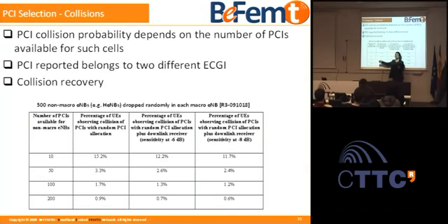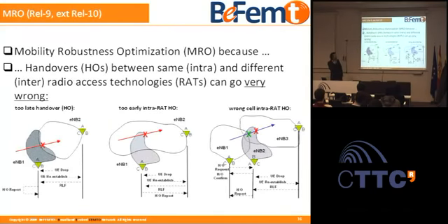The remaining 200 you assign to your femtos which are in the area, and let them choose randomly a PCI without making a lot of fuss. They calculated the probability of any of the 2 choosing the same. It's not 0, but it's very far from 100% either. And maybe algorithms which you had proposed will help even further, getting it down close to 0.